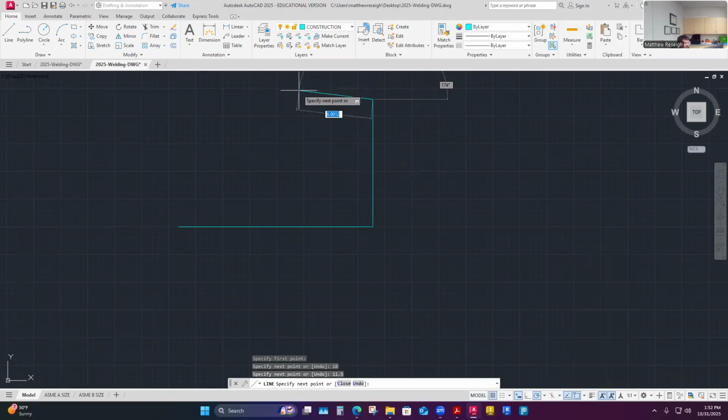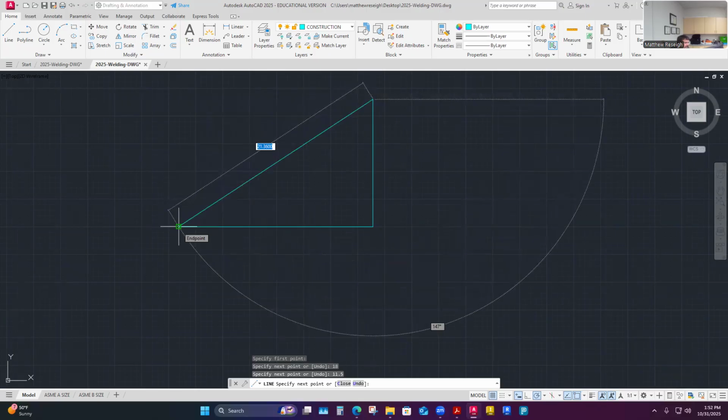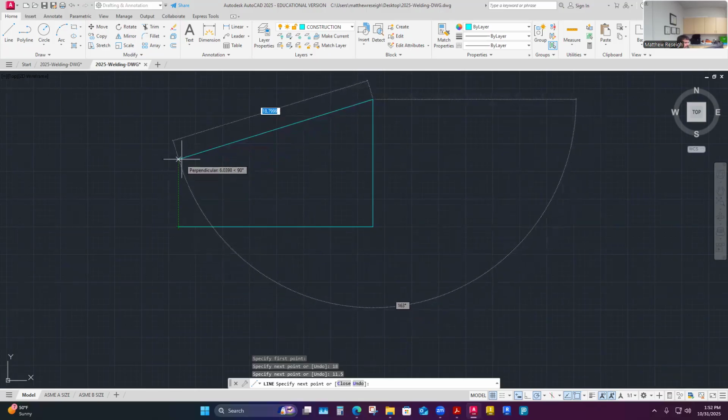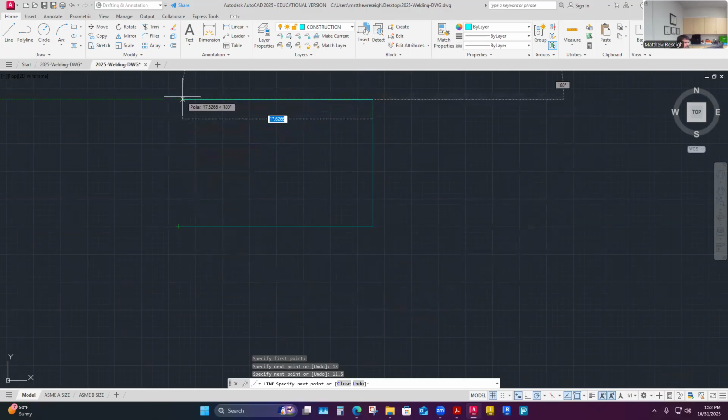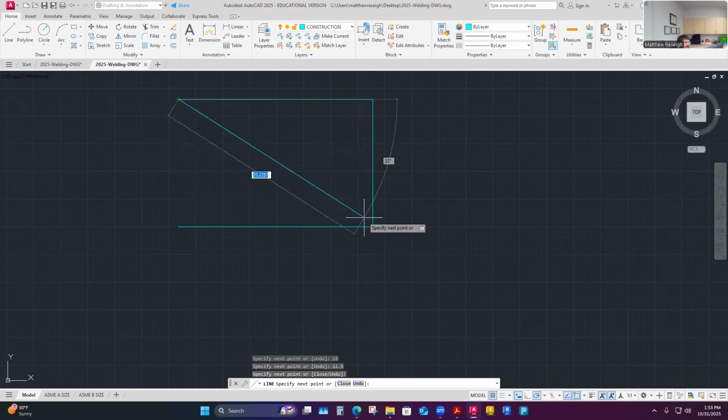What that allows you to do is, instead of entering 18 and hitting enter, I can actually just reference a point in space like this. That's an 18-inch line. And then if I pull away from it, it tracks away from me. I'm going to be able to pull until both of these line up. It knows that I almost scoped in on that endpoint. As I pull across, it's like, hey, there's where you're vertically aligned with that. Is that what you want? It's like, yeah. So you can use that to your advantage. That's what I just did to help you track to the other geometry, which you'll see me use a lot here probably.